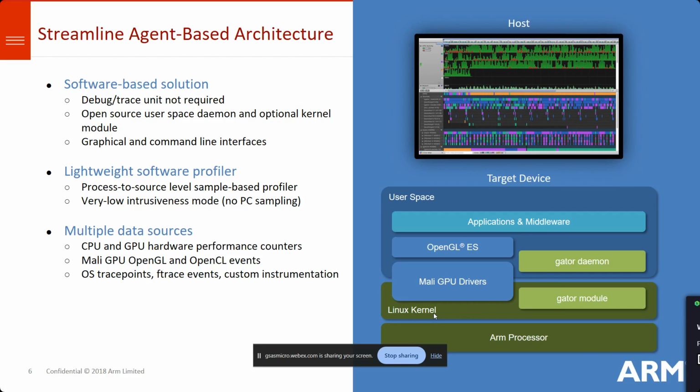How does it collect? Through the counters. Higher-end processors like Cortex-A and Cortex-R have CPU counters. As I was telling, with the help of DS you can have visibility of cache, MMU, MPU. In the cache, you have options like cache fill, cache miss, cache hit. Suppose you want to know how many cache hits happen. That's a positive thing, right? Every time the processor requests data, the data is available in the cache. That's a cache hit.